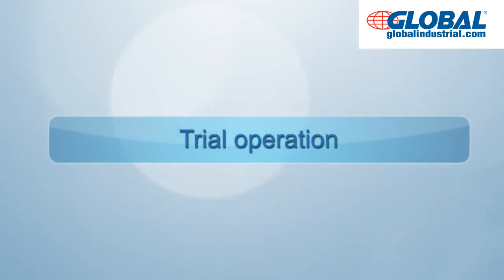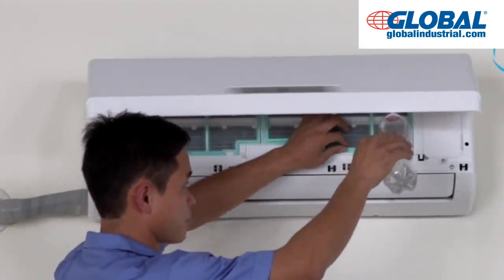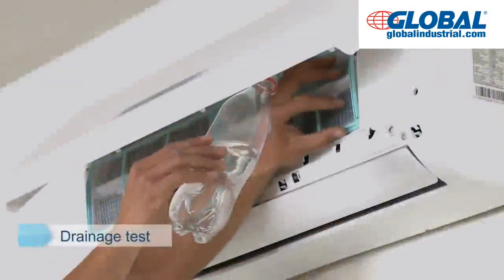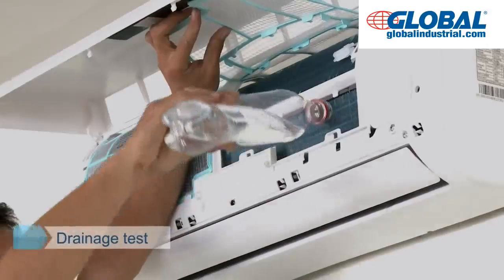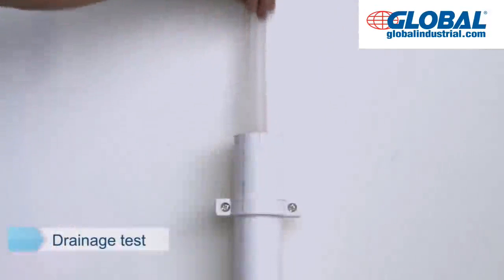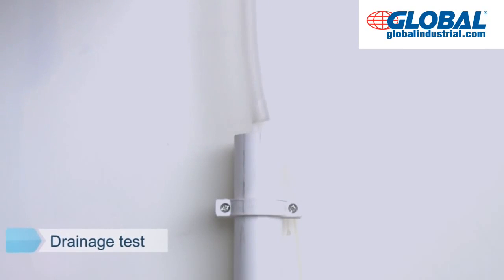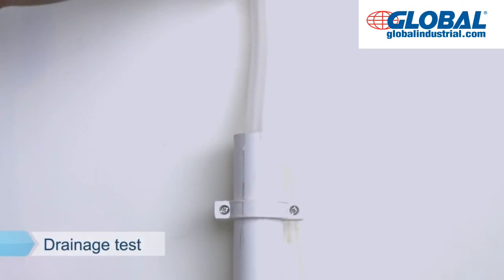Trial operation. Open the panel, remove the filter, and pour certain amount of water slowly through the upper part of evaporator to check whether drainage is smooth. After it is ensured that water flows through drain pipe smoothly, drain pipe should be inserted into outside drain pipeline.